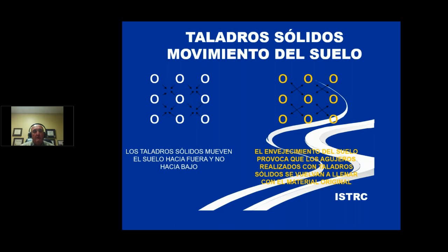There's two ways mechanically. One, we already talked about it. It's either venting, which is just punching a hole in some fashion, and so that's what this is over here. You punch a hole, and what does it do? We push it in, and then we have the compaction going laterally like this and like this into it. So what happens? Well, the holes themselves will stay open about 2 days, maybe 3, and then they'll just collapse in on themselves.